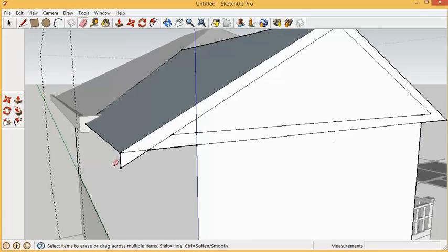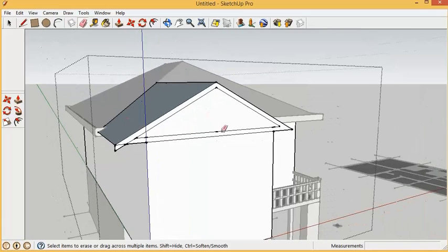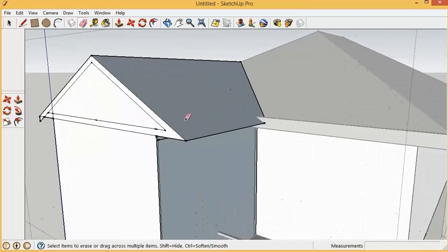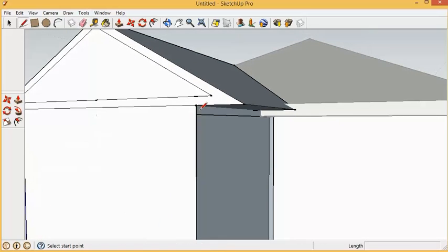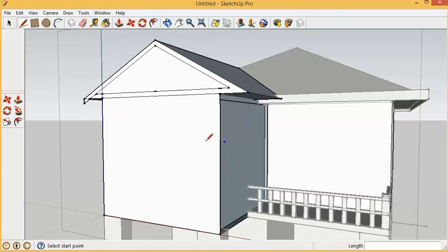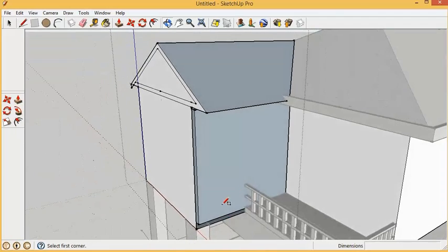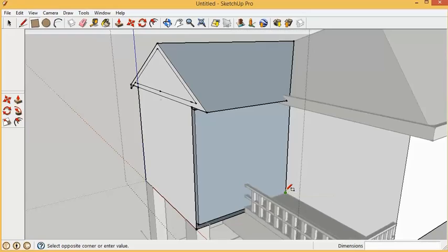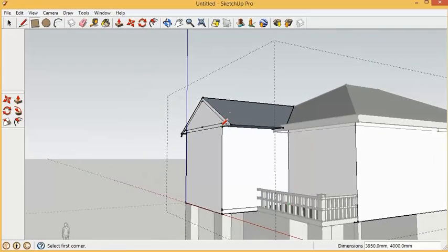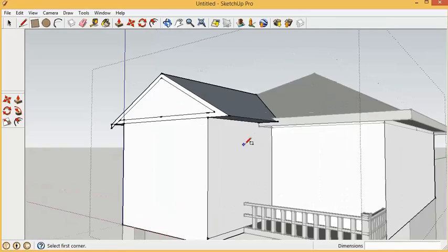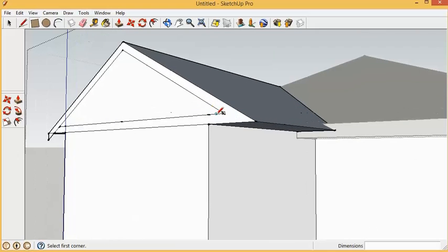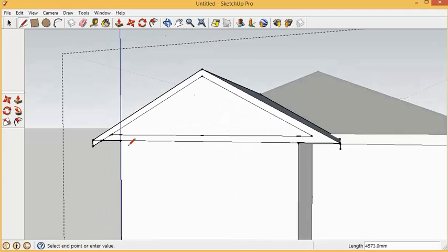When you work with textures, there are sometimes when you'll need to apply a texture to a curved surface. Now, this can present a little bit of a problem, but let me show you how to do this. We're going to do an outside label to this cylinder here, so basically like a soup can or something like that. So we can bring in a texture by importing it, like we did last time. So let's do File, Import. Basically what we're doing is we're setting out a base. And we have a soup label image. Now, I want to make sure that we use this as a texture. And let's go ahead and press that it fills it in.